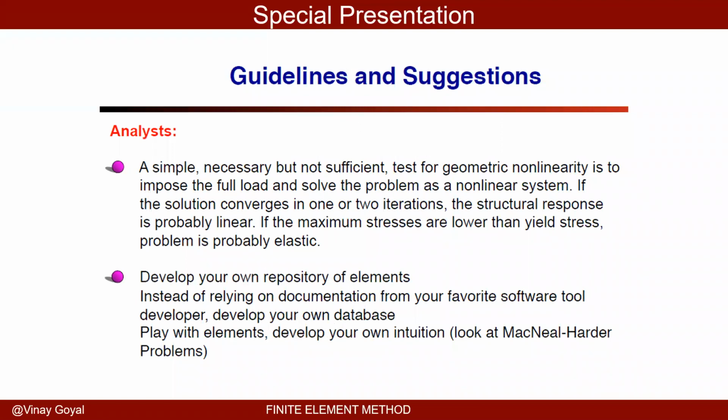A simple test is to check for geometric nonlinearity: impose the full load and solve the problem as a nonlinear system. This is extreme. Most of the time, you don't need to do this. But keep in mind, as an extreme, you may have to do this.